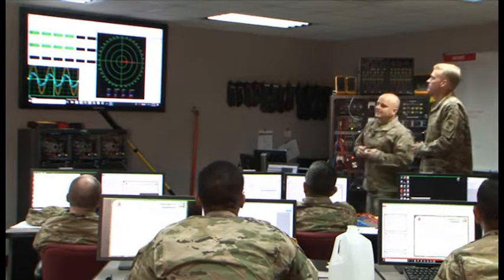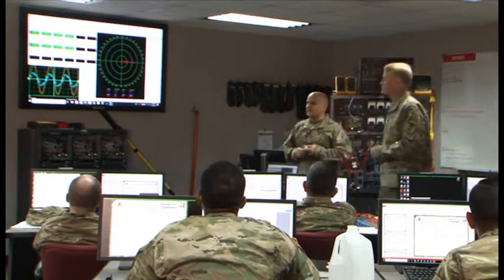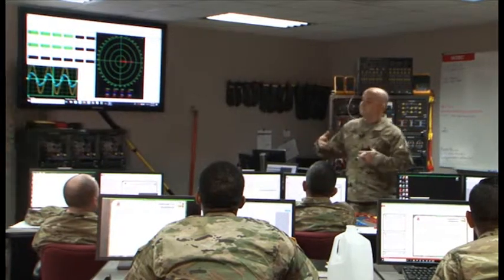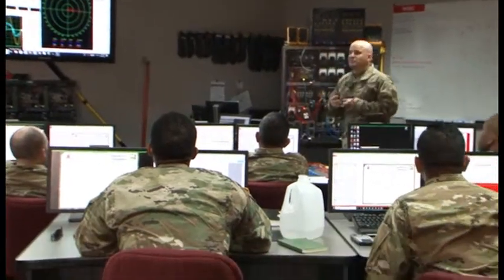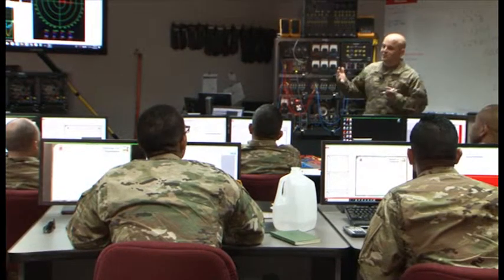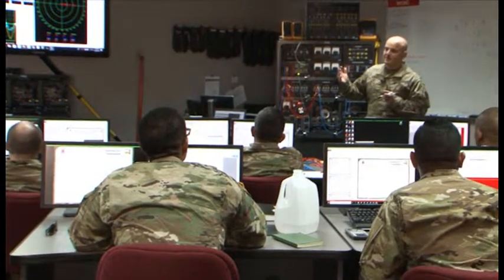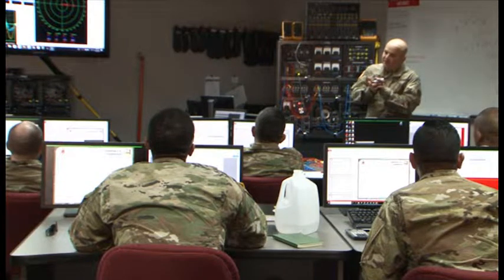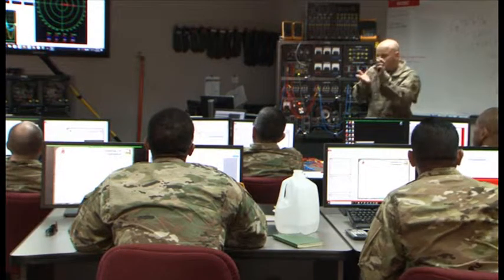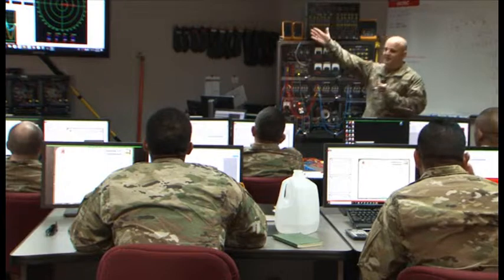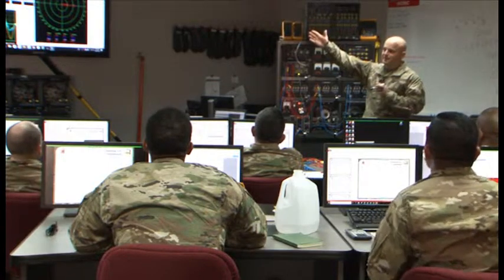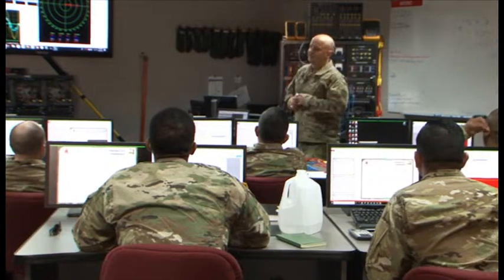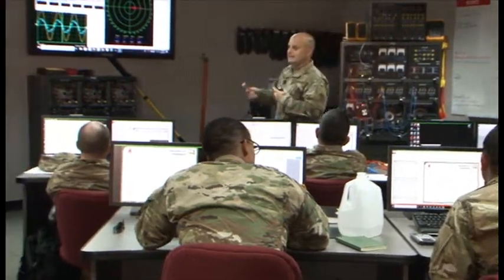And so one of the things that it talks about in one of these labs is power factor correction. And power factor correction is still trying to get the same amount of P out there for the load, but minimizing the actual line current that's out there. And you're minimizing the line current because you're bringing that phase angle as close to 1 as you can, which is thereby reducing it. You are not creating such a long hypotenuse. That makes sense? And so we think about the distribution system, and we're going to talk about this when you get into the components of distribution block, and I kind of hinted at it the other day.